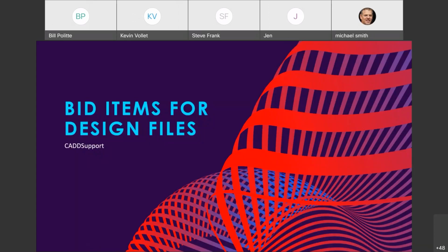For my portion this time, we're going to talk about bid items. I know they were in PowerGEOPAK back in the day, and DNC Manager had some pay items involved with what you could place on the plan. ORD also now has that ability. It takes quite a bit of setup, but the setup is pretty well done. For now, we've got all of our current pay items available to add to different geometry on the screen. And our civil elements, if they have a pay item associated, will have it attached to those feature definitions.